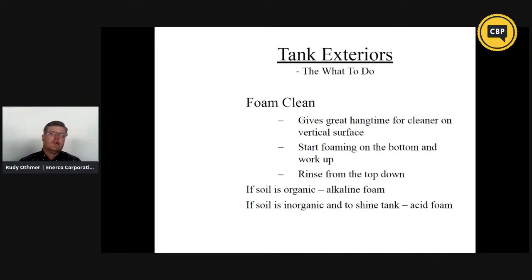If it's inorganic, or to create or maintain the pristine, shiny look on the tank, you want to use an acid-based foaming product. And frequently you'll use the alkaline foamer, followed by a rinse, followed by the acid foaming for the sparkle.